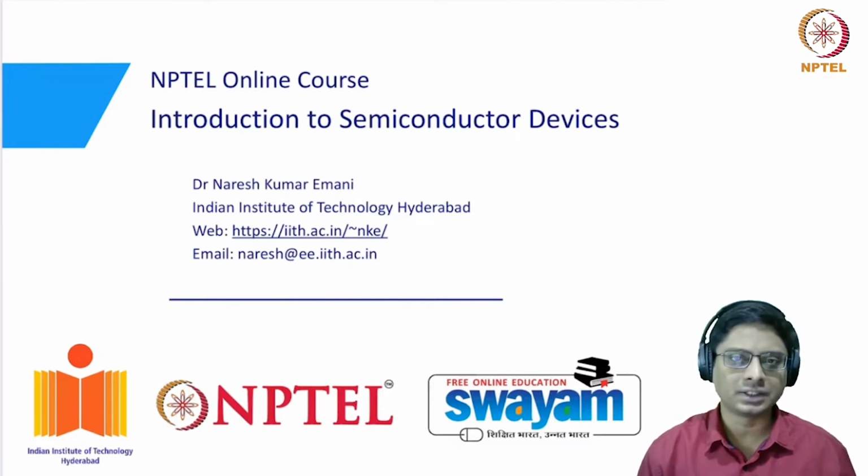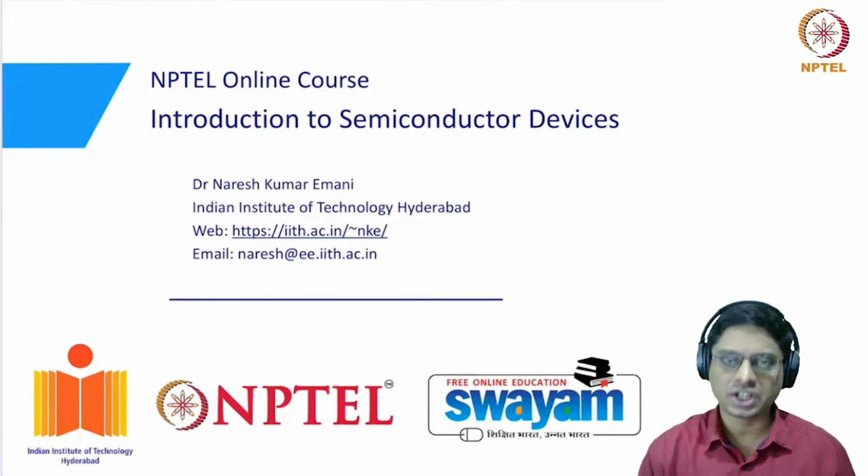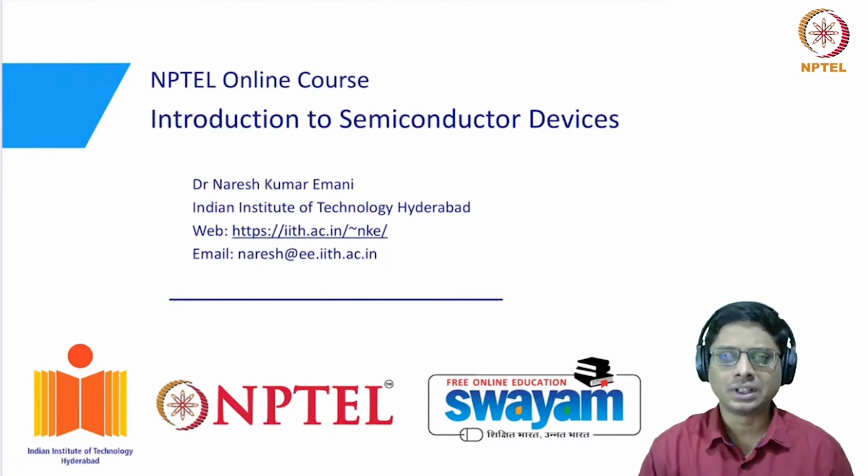We have studied the electrostatics of the MOS capacitor in great depth, and then in the lateral direction from source to the drain, it is essentially two PN diodes which are back to back, right? So we have seen how there is a barrier formed across a channel, because of which current will not conduct, and that barrier can be changed by applying a gate voltage. So this is the essential physics of the MOSFET.